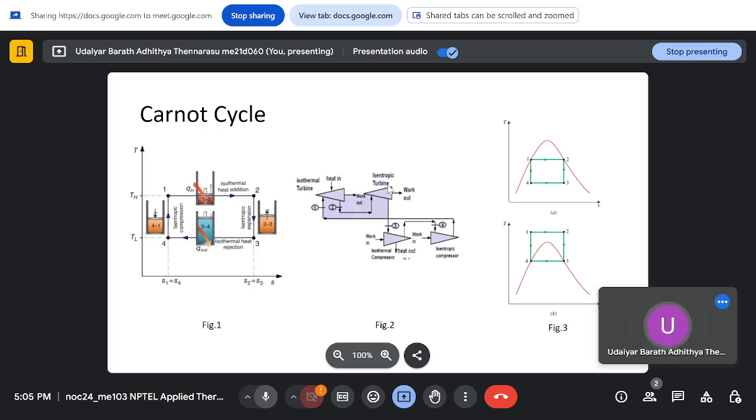So in the ideal assumption of a quasi-static process which we assume, that has to happen. You go with a small incremental amount, and let it come back to the same temperature. So these are all practical difficulties, and it will also become very bulky, with bigger size compressors, and so on, which we discussed during the Carnot cycle.